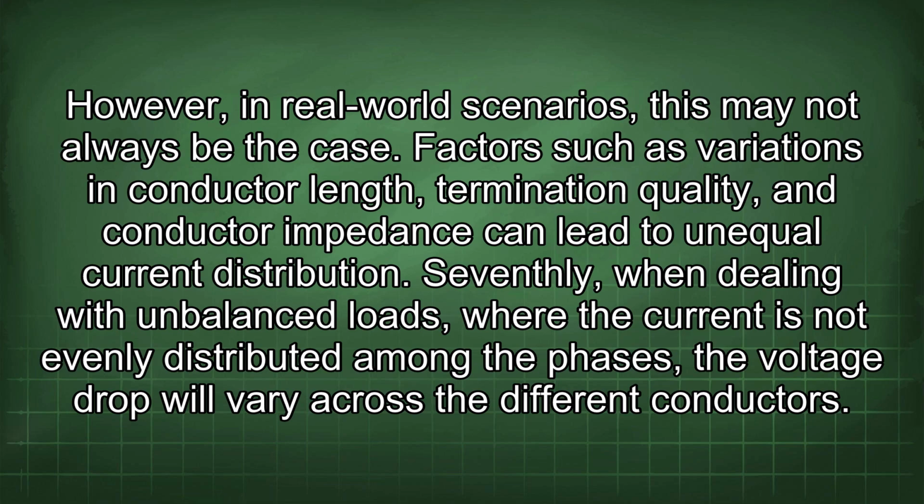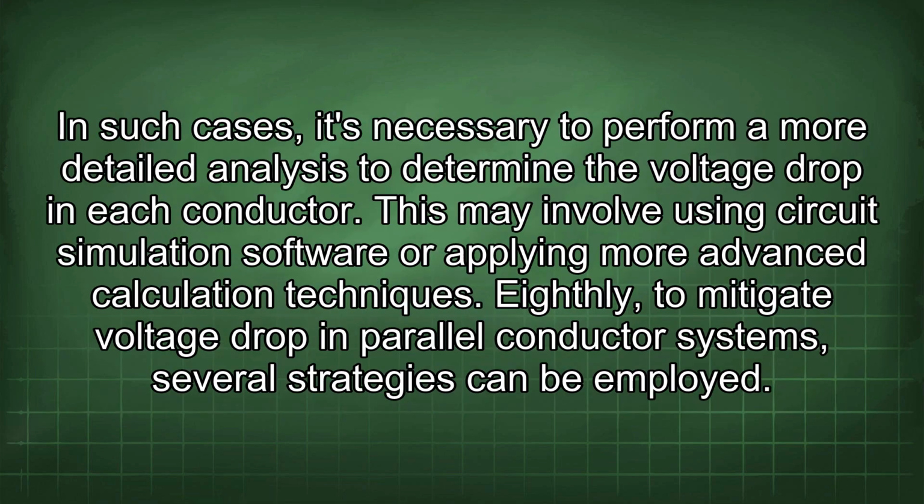Seventhly, when dealing with unbalanced loads where the current is not evenly distributed among the phases, the voltage drop will vary across the different conductors. In such cases, it's necessary to perform a more detailed analysis to determine the voltage drop in each conductor. This may involve using circuit simulation software or applying more advanced calculation techniques.